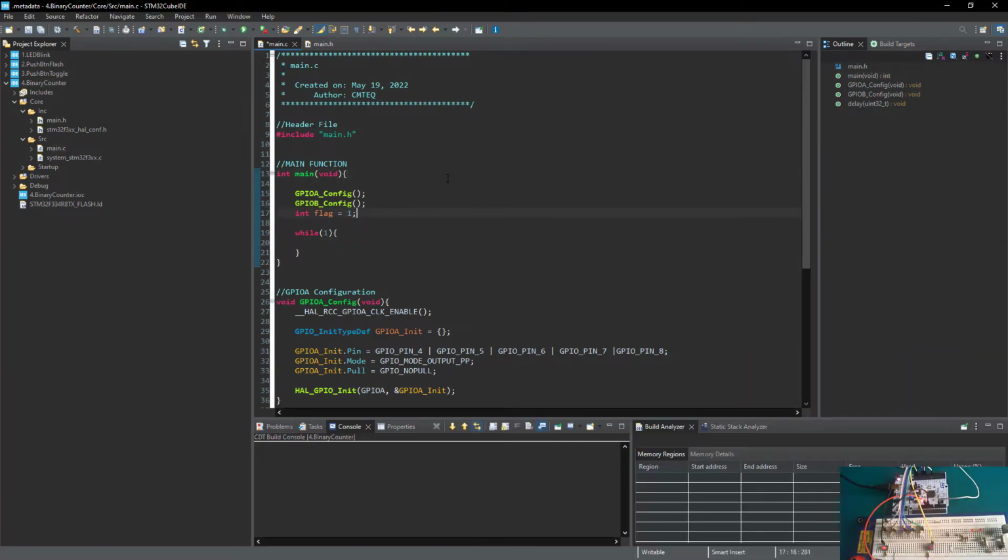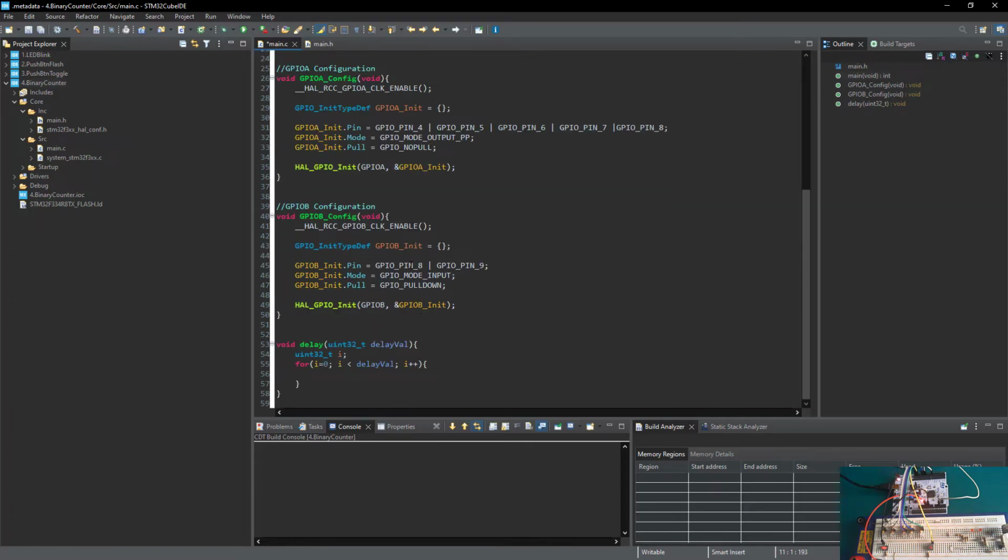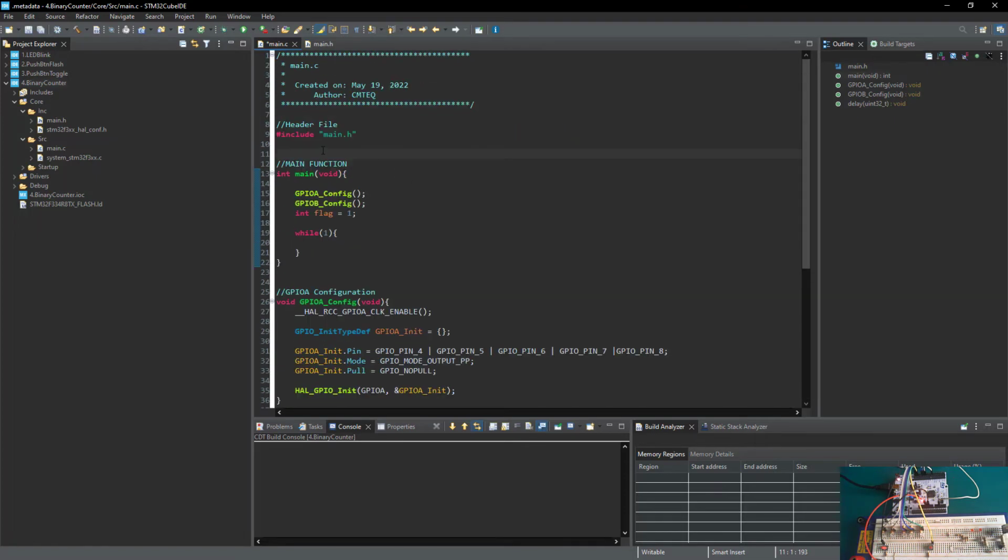Okay, so now the story here is very simple. We've got two push buttons. One button is responsible for initiating the count up, one is for initiating the countdown. But I want these buttons to be called with some readable name, right? We know that we've set them here to be pin 8 and pin 9, so I want to give them human-readable names. I'm going to write some preprocessor defines here.